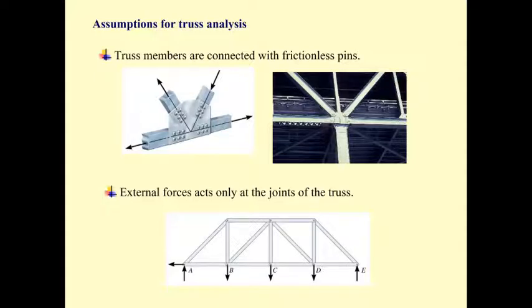And then after we finish statics, we come to the mechanics of materials. In the mechanics of materials, when we design the truss, we use the allowable stress, and the allowable stress is the yielding stress divided by 2. So the behavior of the truss member under the applied force is going to be linear elastic. This is the third important assumption.